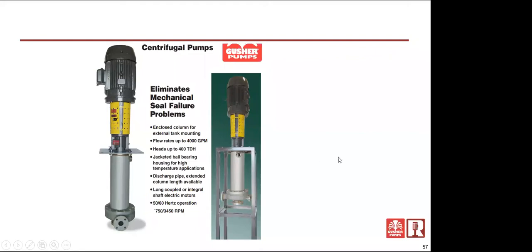Now, one of the minimum constraints here is that this cover plate, this area right here, there's bearings in this bearing housing. This cover plate that's at the top of this stand has to be above the highest liquid level that that tank would ever have. So that maximum liquid level has to be below this plate. We can mount this up in the air 30 feet, that's no problem. We can make this pump longer to get that suction down lower.